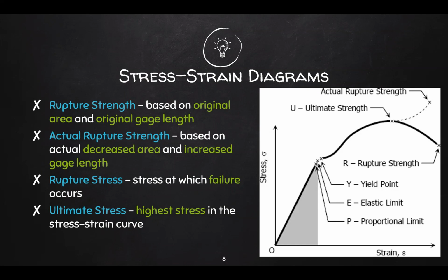So in other words, the proportional limit determines the greatest stress that is directly proportional to strain. So anything above that, stress is not proportional to strain anymore. Hence, that's why we call that proportional limit. So after your proportional limit, you also see this point, close to that, your elastic limit.